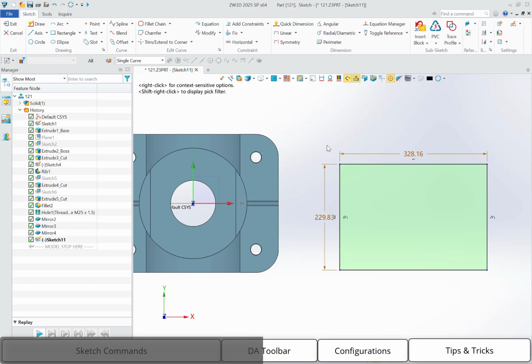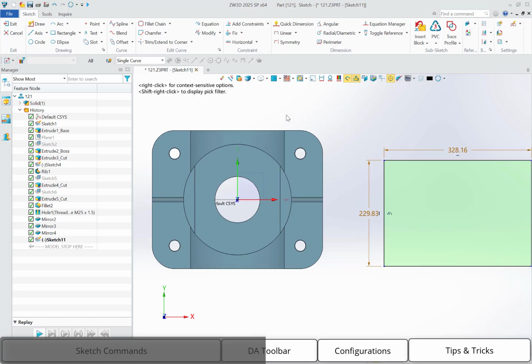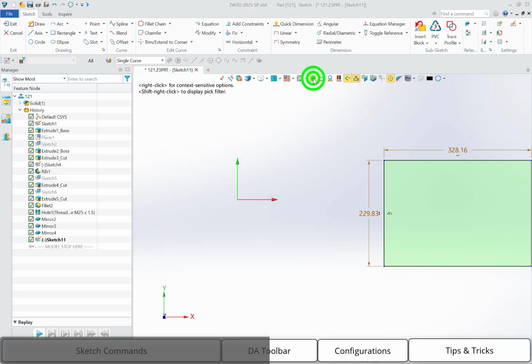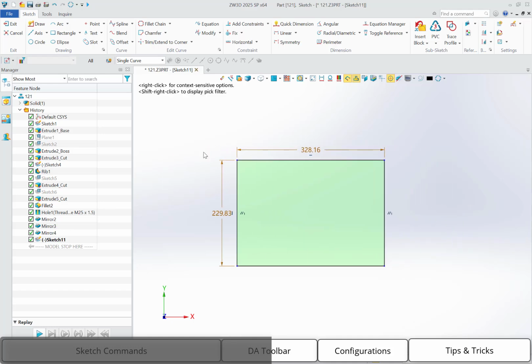And then next, I'm going to show you the show target command. Sometimes we don't want to take anything from the existing shape, and we think it's not so clean for our sketch. In this case, we can use show target, so it will hide the unnecessary back shapes and only show the sketch we are working with. And the next are the two switchers to switch the dimensions on or off, or to switch the constraints on or off. Very easy to understand.